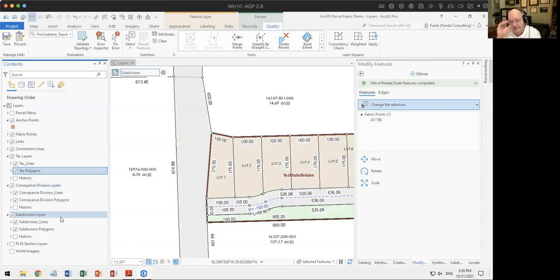So to answer that question, if we're talking about moving points, it does move things, even if they're turned off and not being displayed. So be aware of that when I make any of those adjustments, especially with the Align Parcels tool. Initially it's using the transform tool, which is moving points. That's how it makes those transfers.